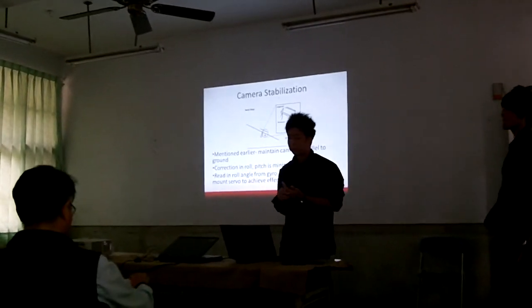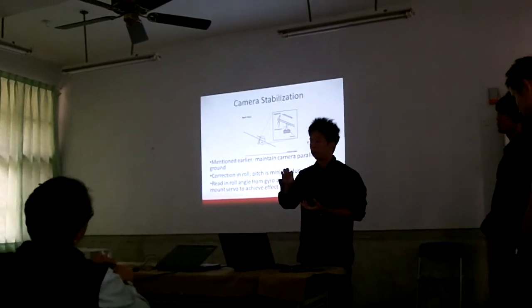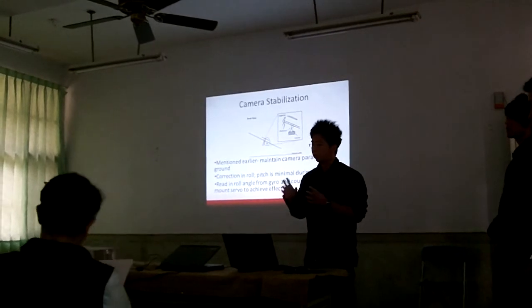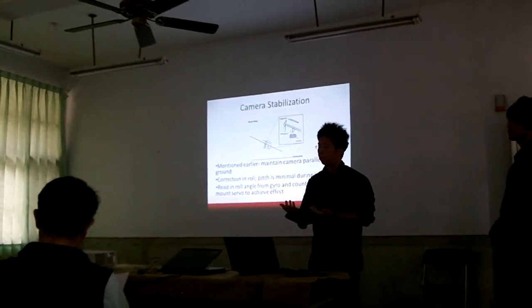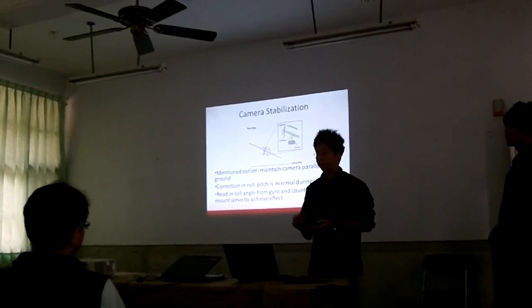So what we do is, APM already calculates from its 3 accelerometers, and it's already filtered. We can read out the instantaneous roll and bank angle of the aircraft at any given time.